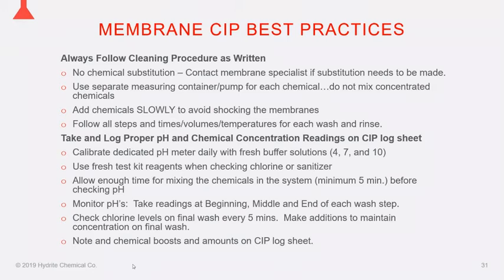And a couple of notes on where you take your chemical samples when you're going to check your system, okay? On UF and MF systems, of course, we know those have very large membrane pores in comparison to ROs and nanos. You're essentially going to have the same chemistry on both sides of the membrane, either in the permeate stream or in the concentrate stream, provided that the chemicals are sufficiently mixed in. So it doesn't really matter where you take your chemical sample.